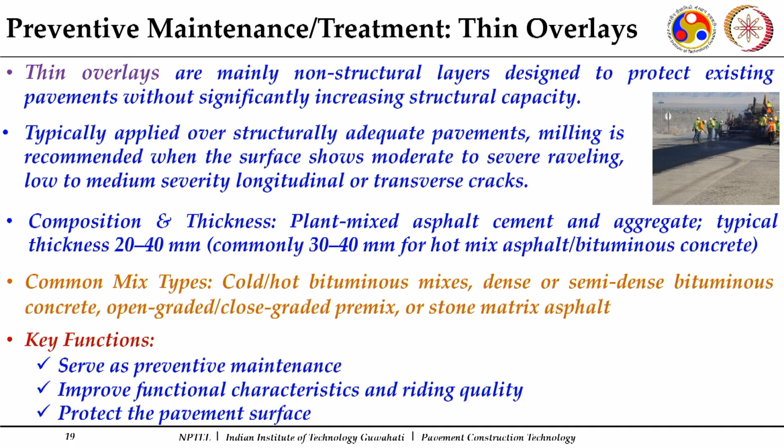Now, thereafter the other application is in terms of thin overlays. Thin overlays can use certain mixes, say the close graded premix carpet, semi-dense bituminous concrete or bituminous concrete. These are certain thin overlays which can be applied, and the thickness is usually less than 20 mm.